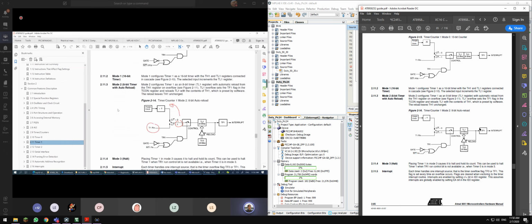And remember, all the clock is coming into the AT89S8253. Let's assume I'm using 12 megahertz, divided by 12, so what is coming in is 1 megahertz.